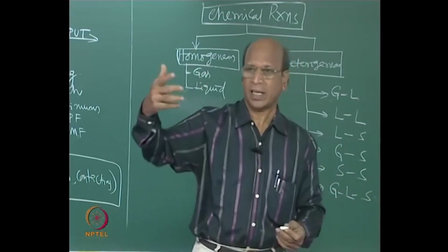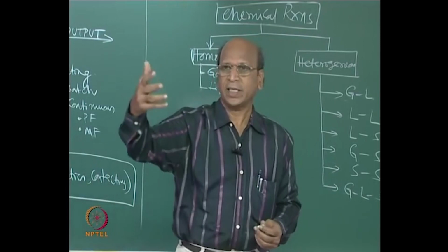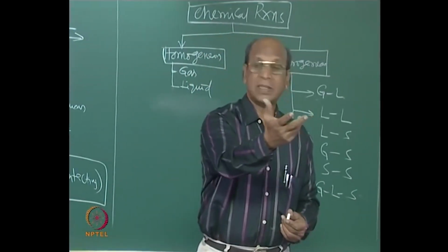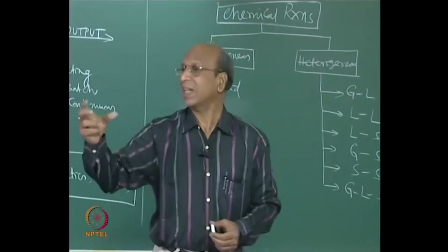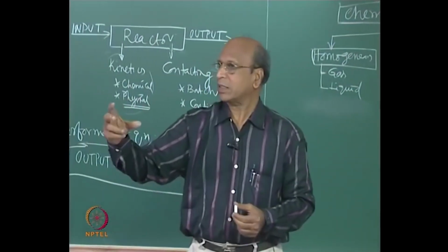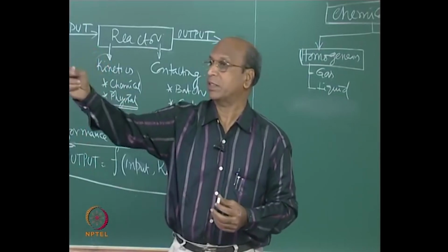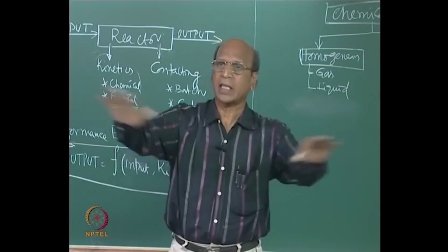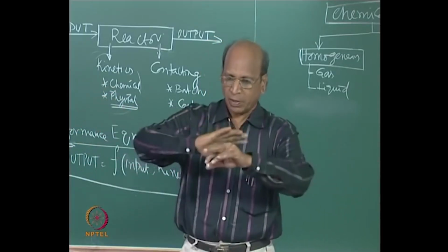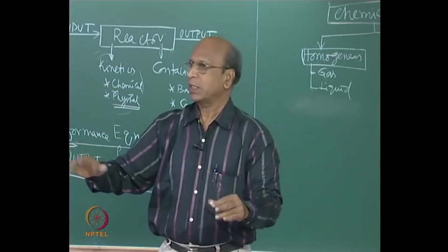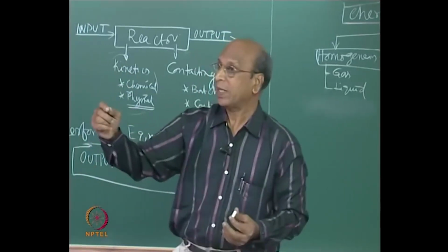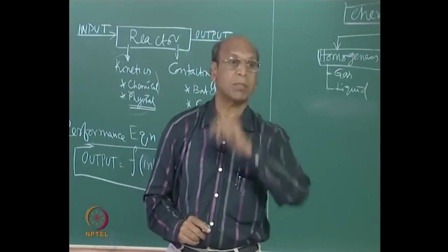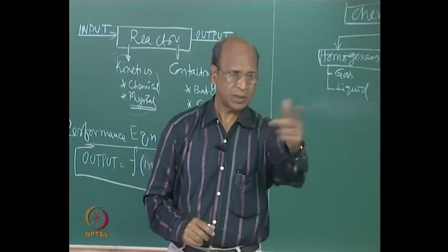But again, problems are there. If so much heat is generated inside, then the particle will get what is called thermal sintering. When sintering occurs, naturally you will not have the effective sites, the active sites of the catalyst; they will die. It becomes like a glass surface. If it becomes like a smooth glass surface, then you will not have the defects where catalytic activity goes on. That is called thermal sintering, and we also have thermal deactivation.